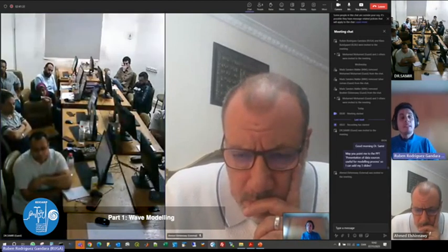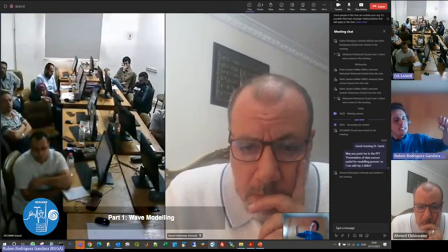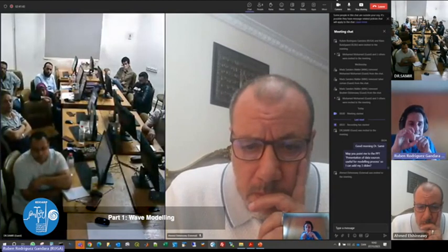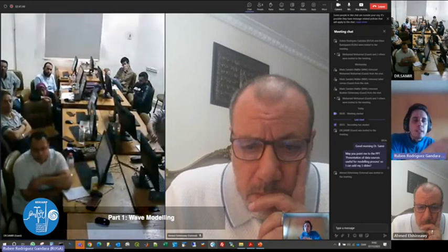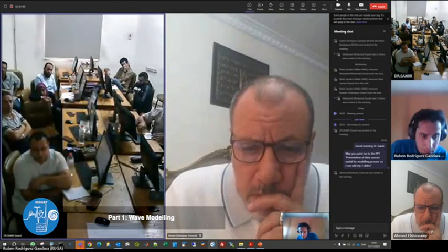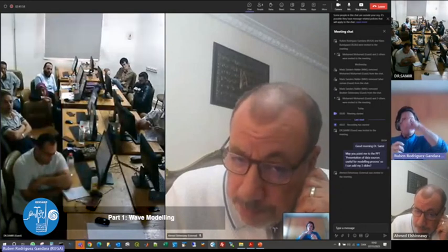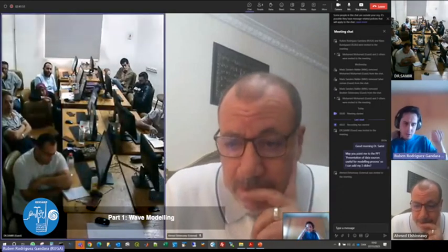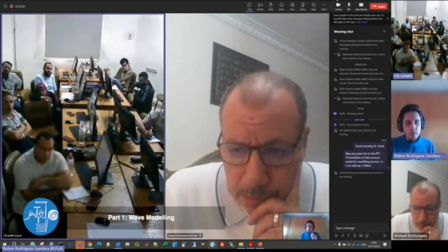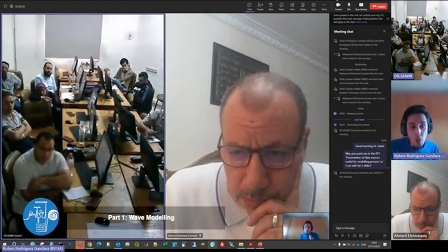So here it is the same thing. Mike can give you an estimate if you are considering the diffraction of, let's say, an island in the middle of the domain, and how that little blockage is going to impact what is happening on the coast. Then that's fine, it can do it. But if you're interested in what is happening right behind the island, or if you have a harbor in your model, it will not give you the right answer. So for that, you will need to set up a different model, a model that is capable of resolving the phase.